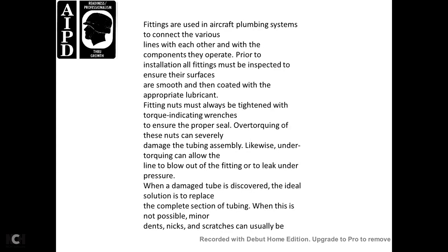Fittings are used with the aircraft plumbing system to connect the various lines with each other and with the components they operate. Prior to installation, fittings must be inspected to ensure all surfaces are smooth, and they can be lubricated with appropriate lubricant. Fittings must always be tightened with torque indicating wrenches to ensure proper seal. Over-torquing these nuts can severely damage the tube assembly. Likewise, under-torquing can allow the line to blow out of the fitting or leak under pressure.